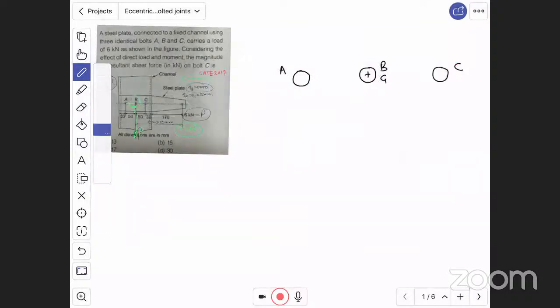तो देखते हैं, पुट करते हैं इसको हम यहाँ पे, right? Let us solve this. तो at G location we will put force P as it is, which is nothing but 6 kilonewton, right? And there is a torque also acting in clockwise direction. This torque is equal to P into E. E is given 250 mm. We have calculated these all values, right?